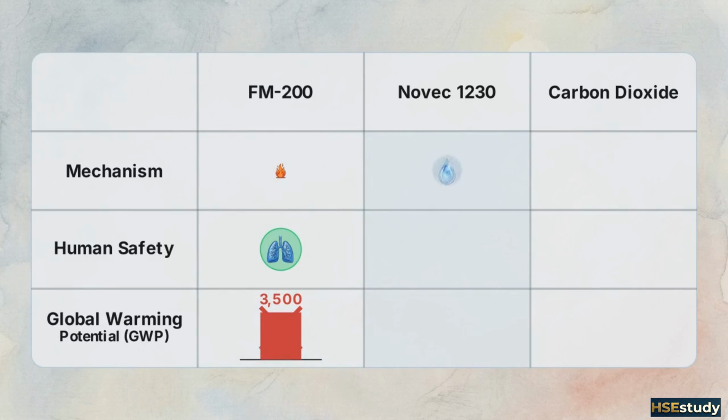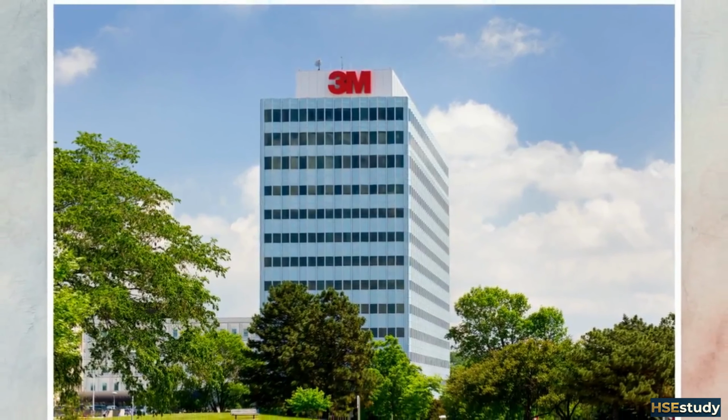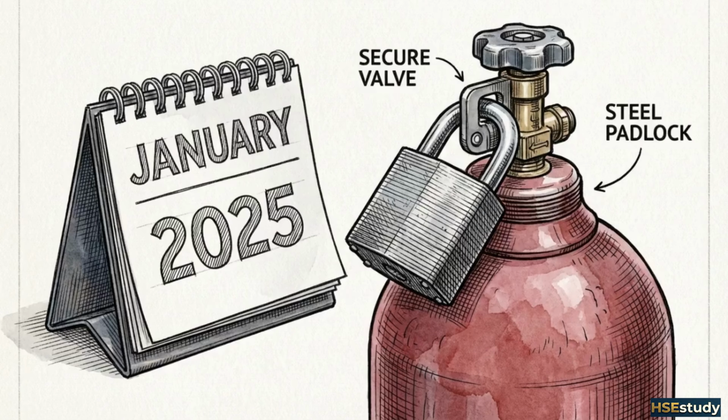Novec 1230 is a fluorinated ketone, stored as a liquid but discharged as a heat-absorbing gas. With a GWP of just 1, it became the preferred environmentally friendly alternative to FM200. Despite its performance, the industry is facing a severe supply crisis for this specific compound. 3M is voluntarily ceasing Novec production by 2025 due to global regulations on PFAS, or forever chemicals.